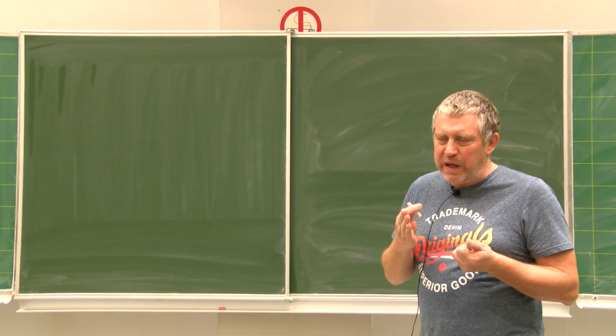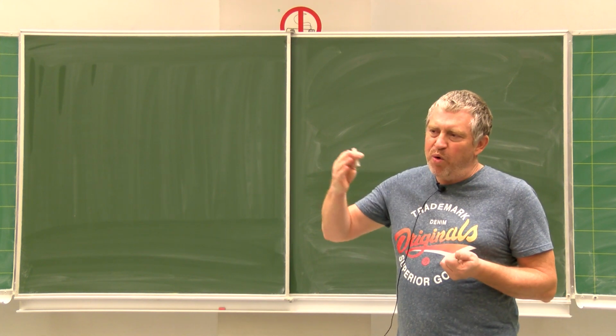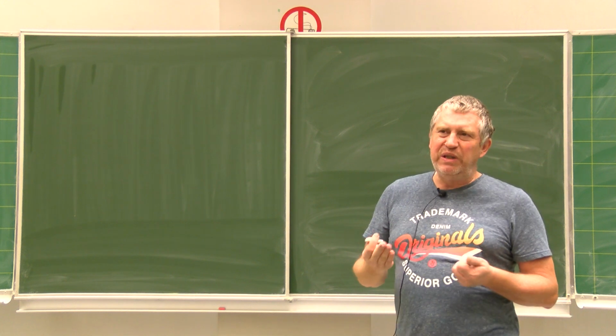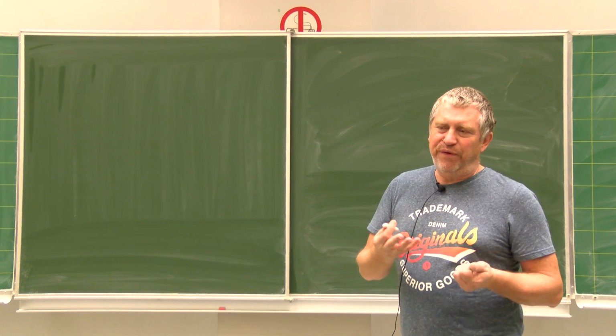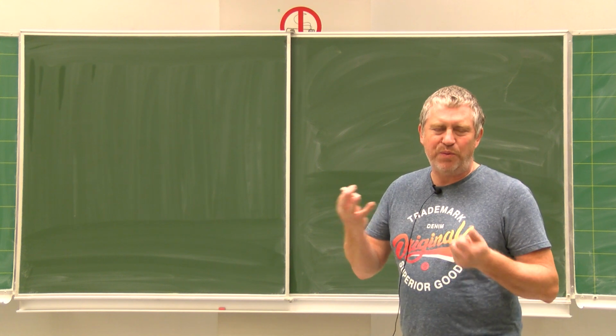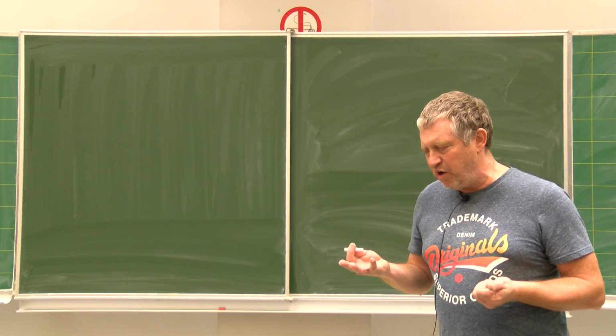So we are going more and more towards TSFC reduction, so we are going into the opposite direction for the F over m dot. The F over m dot is worse and worse. So this is quite normal.